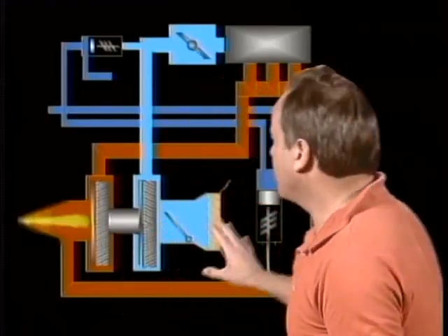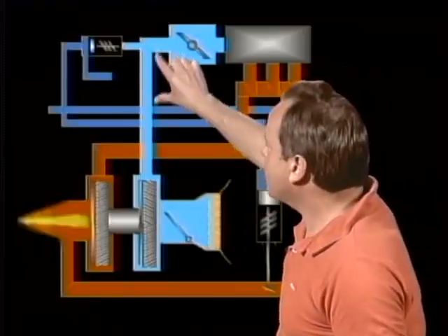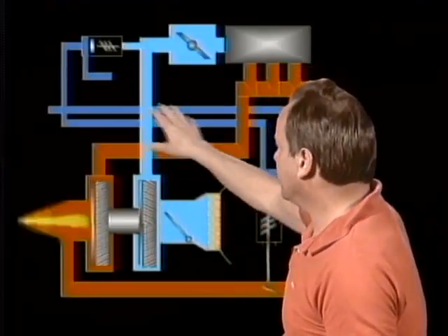All right, there is another thing in this system where we're talking about a turbo-normalized system, and that is called the pressure ratio controller. And it says, look, we don't ever want the ratio between deck pressure and ambient air, the outside air pressure, to be more than 2 to 1, because you'd be overheating the air, compressing it too much. This system is designed to only take so much.